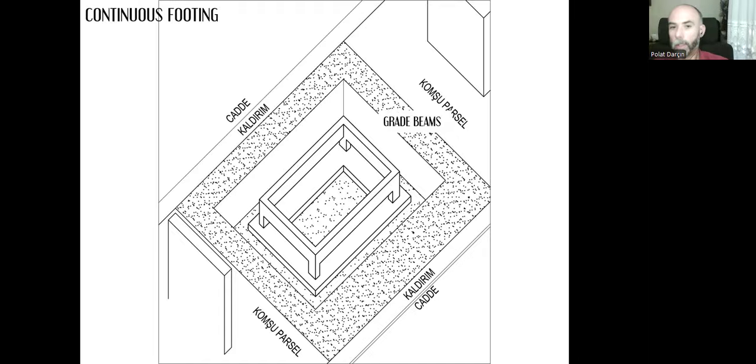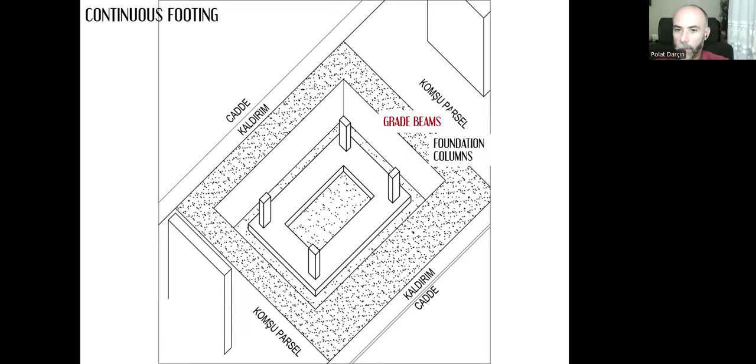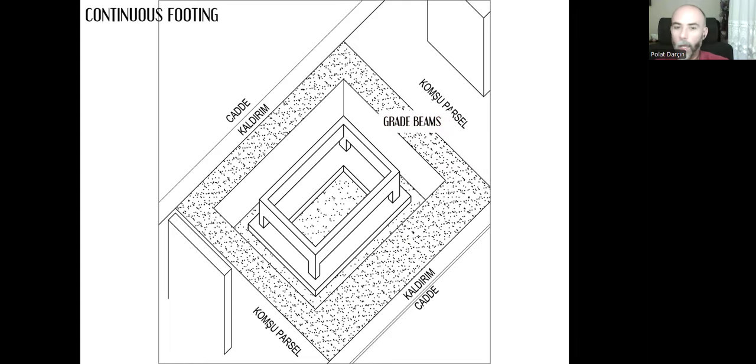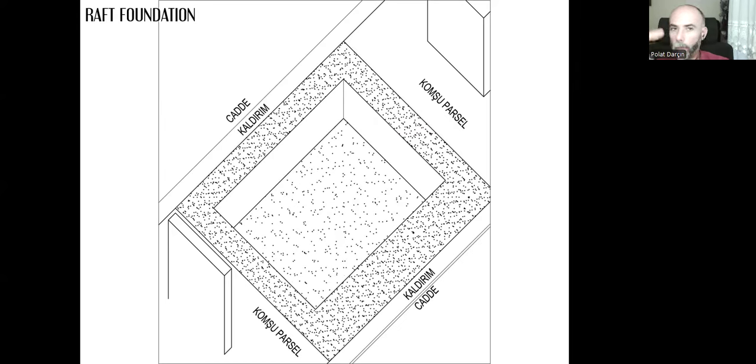But let's imagine the bearing capacity is still not enough. Even if we do this continuous footing, we still exceed the bearing capacity, or there are some other risks, like there is underground water and it has this buoyancy effect. Then we will be needing a raft foundation.